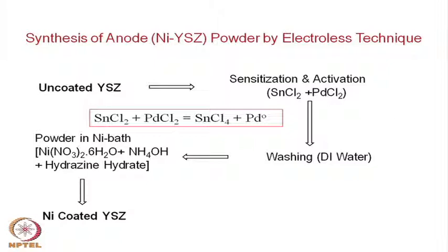So, instead of random mixing, normally, as I mentioned earlier, nickel oxide and YSZ are mixed together and then heated to high temperature to sinter them and make a bonding between them, and then nickel oxide is reduced in a hydrogen atmosphere so that nickel is produced. It of course helps develop the porosity as well. Once nickel oxide is reduced to nickel, oxygen goes out and it produces a sufficient amount of porosity. That is also an advantage.